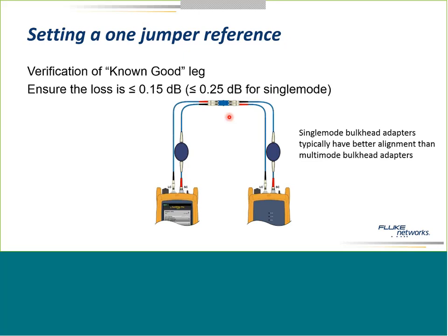Well, as long as you haven't removed the cord from the output port, you haven't changed the alignment on the output port here, turn the testers on. Let them warm up. We want to get them to room temperature, maybe 15 minutes, depends on where they've come from. You're in the far north and you're coming out of 20 below zero, they've been in your car 40 below zero, it's going to take them a little bit longer to warm up. But you're coming back from lunch. They're still at room temperature. Give them about 15 minutes to warm up.